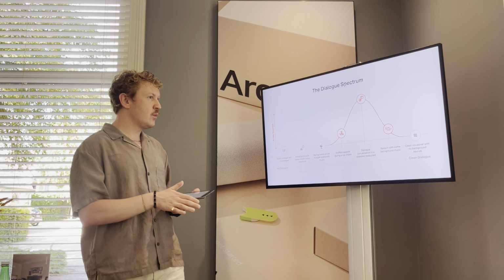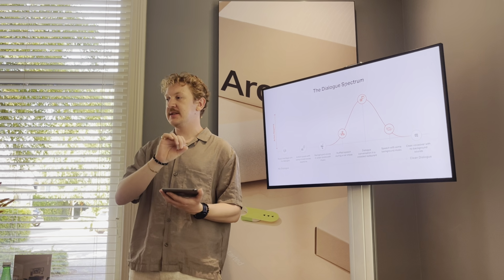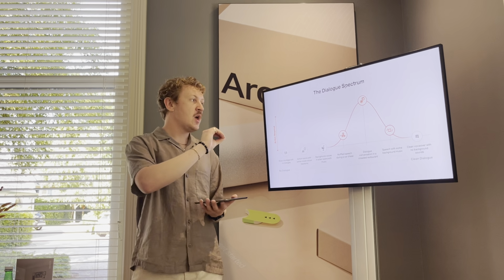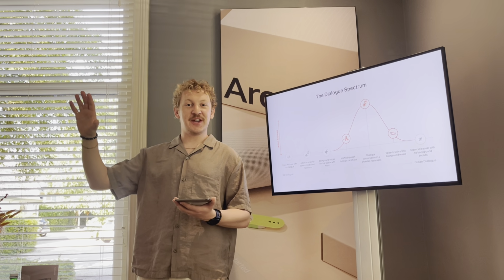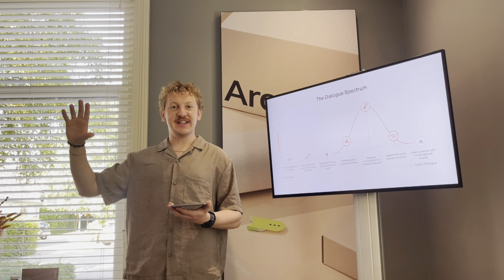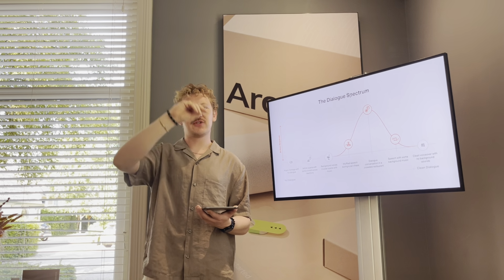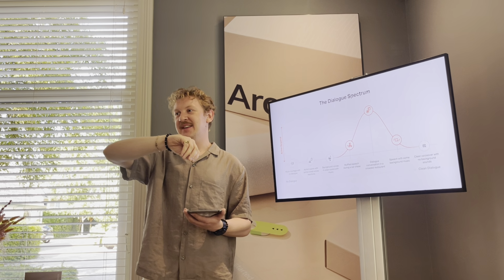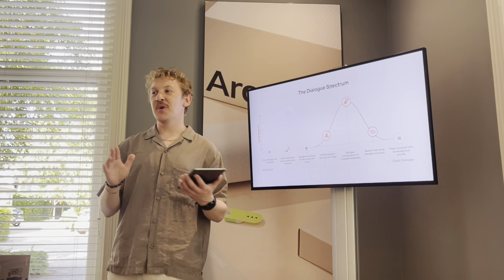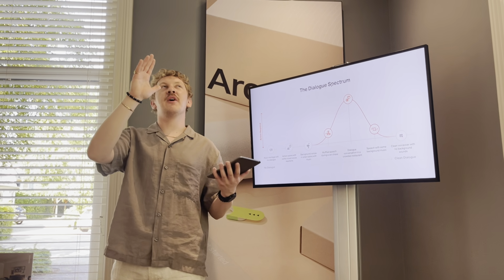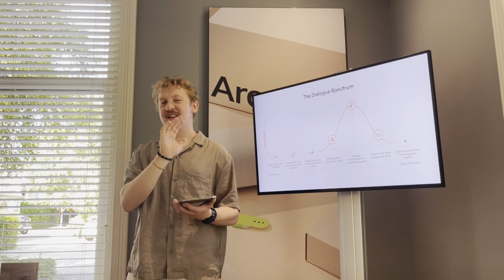So using the extracted AI signal, this source separated signal, we can compare that to the original center channel, and we can say, what is the energy difference there? If there is no correlation between extracted and the original center channel, then we know that there is no dialogue, because if there's nothing on that extracted channel but there's loads of energy on the center channel, we don't do anything.